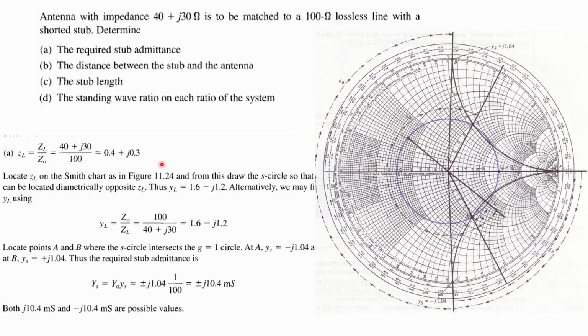Similarly x equal to 0.3 will also be at this point. So r equal to 0.4 is this curve, this one curve, right? This is your r equal to 0.4 circle, and x equal to 0.3 circle is this one. This is the semi half circle, which is x equal to 0.3. So draw this one like this and this. The intersection point is your ZL.